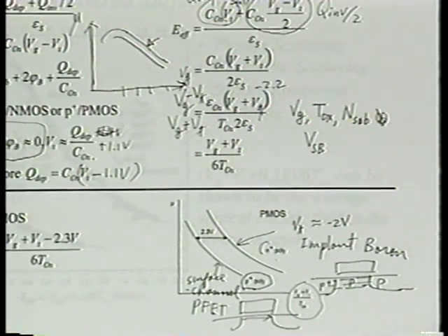I tried to give you some answers with phonon scattering as an example, by saying if the vertical field is strong, perhaps there's a wave function tailing into the gate oxide, and you can have more scattering. Or maybe because the ground state energy is higher, you end up with a higher density of states and more scattering. Is that right? And certainly if it's due to surface roughness, then the argument is that the stronger the surface field, the closer the charge is to the surface, therefore there's more surface scattering.